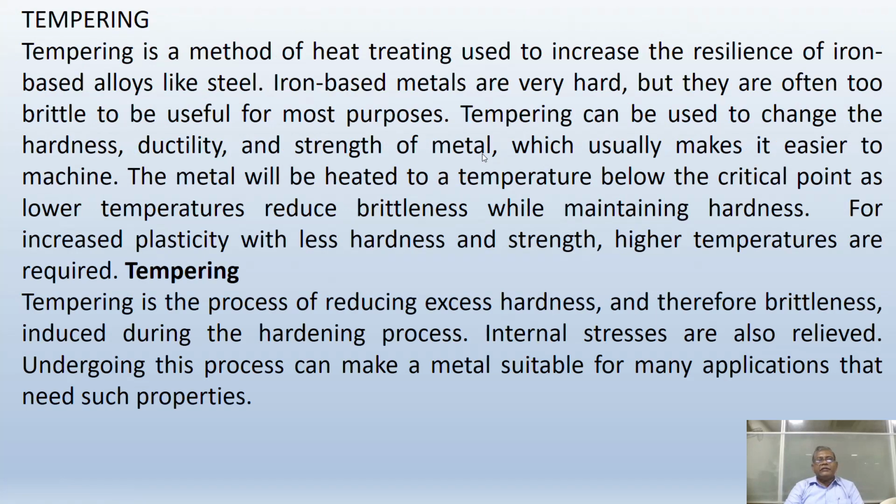Tempering is a method of heat treating used to increase the resilience of iron-based alloys like steel. Iron-based metals are very hard, but they are often too brittle to be useful for most purposes. Tempering can be used to change the hardness, ductility, and strength of the metal, which usually makes it easier to machine. The metal will be heated to a temperature below the critical point, as lower temperatures reduce brittleness while maintaining hardness. For increased plasticity with less hardness and strength, higher temperatures are required.